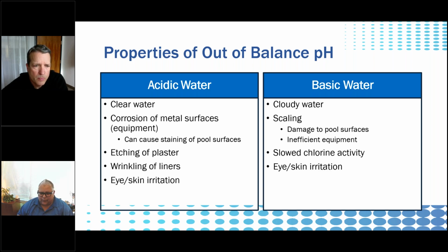A lot of people get out of a pool and they say, oh, I'm itchy. That's just pools. You should never be itchy when you get out of a pool. If you are, there's something wrong in the water balance. It's not the chlorine. It's probably the pH being out of balance and causing your skin and your eyes to have a reaction to it. So always, if a bather ever says they're uncomfortable for any reason, always look at your water balance, because normally there's a parameter, usually pH, that's out of place.